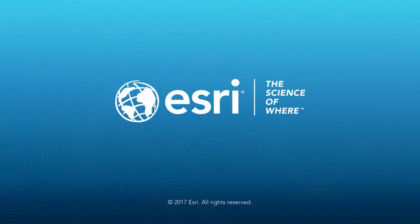Well, I'll follow on real quick. Our business partner, Safe Software, has a product called FME, Feature Manipulation Engine, and we could take all comers of spatial data. You could start with PDF data if that's all that you had, right? So we can take the layers of PDF data, geo-reference it, pin it to an absolute XY position in the world just using that tool set, and we can run that in an iterative fashion.